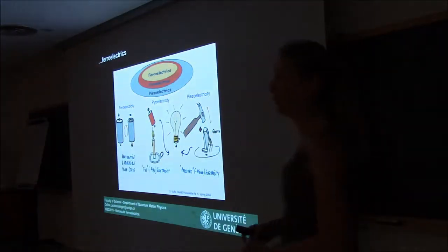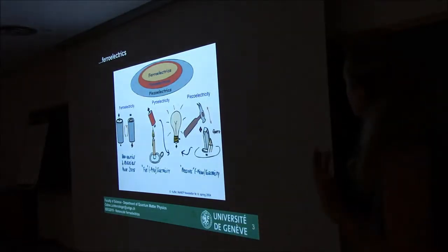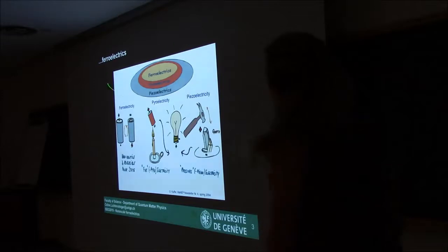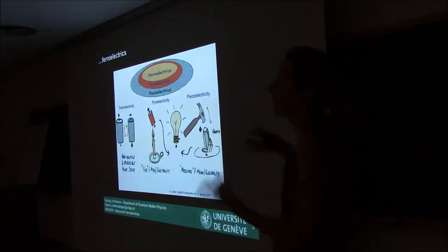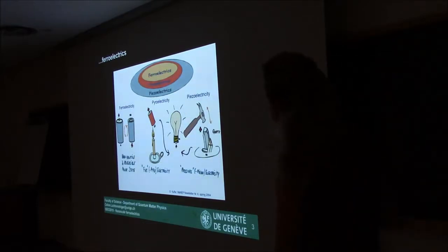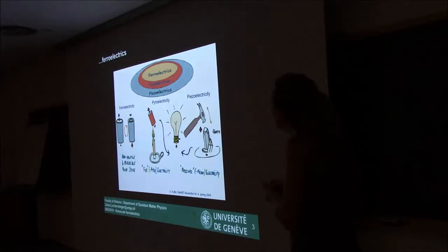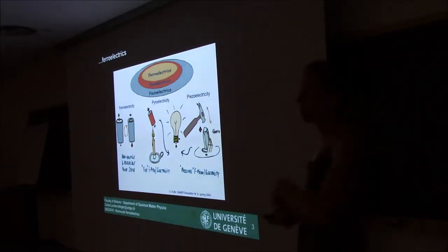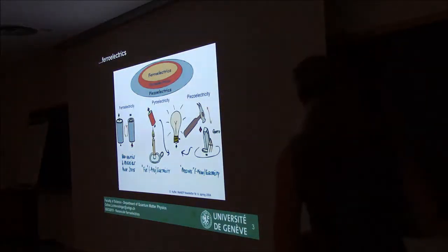So just to put everything in place for everyone, ferroelectric materials are very interesting because this is a class of materials that are among the piezoelectric materials, meaning that when you apply a strain, you get a voltage, or when you apply a voltage, you get a strain deformation. They are also pyroelectric, meaning that their polarization will depend on the temperature. And of course, they are ferroelectric, meaning that their polarization can be switched. And once you remove the voltage to switch the polarization, it's stable. So you have a reversible, non-volatile polar state.